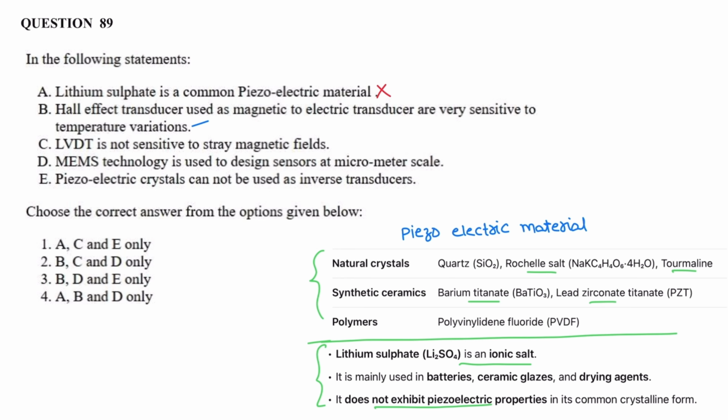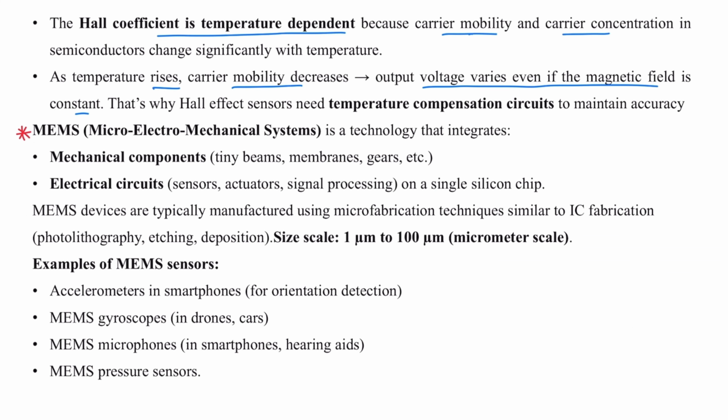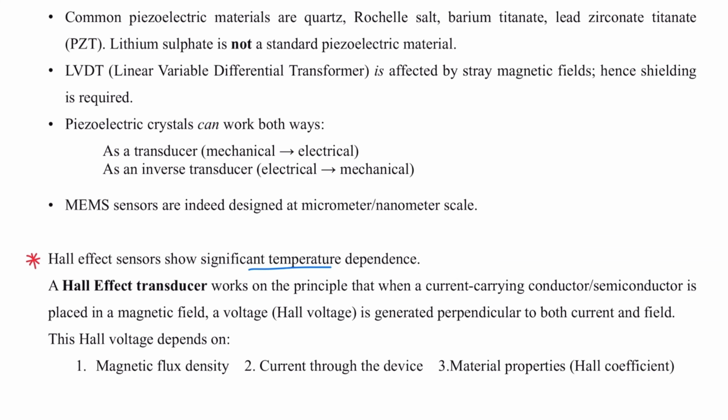Statement C, LVDT is not sensitive to stray magnetic fields. Statement C is incorrect. Linear variable differential transformer is sensitive to stray magnetic fields. LVDT is affected by stray magnetic fields, hence shielding is required.